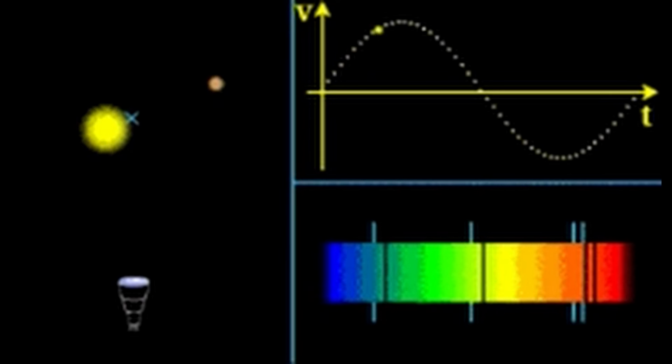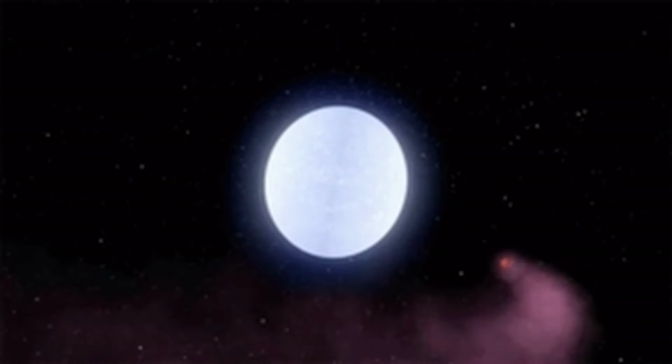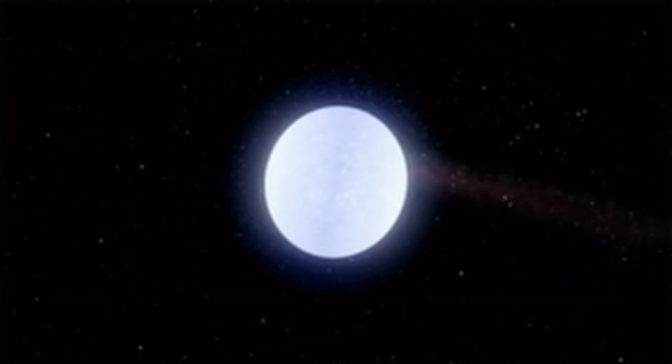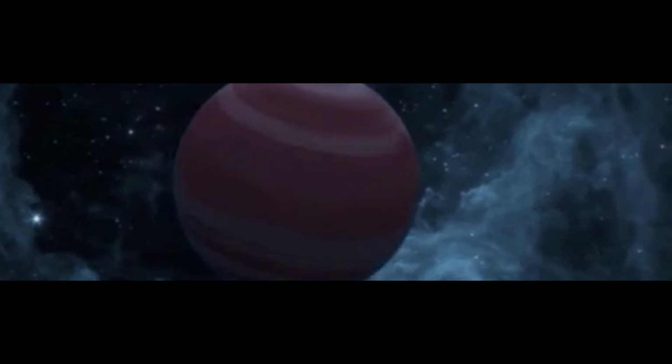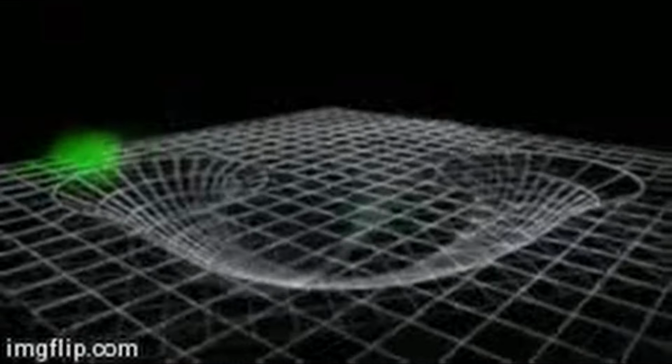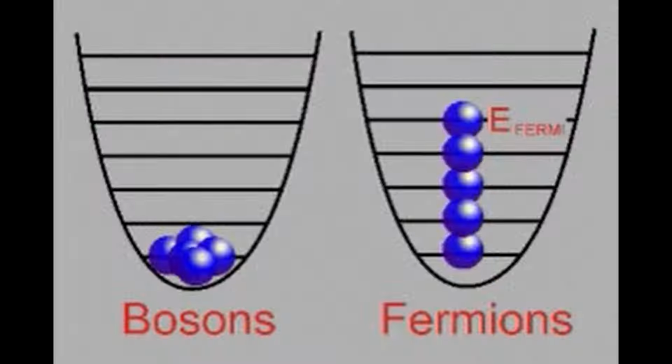5. Attenuation and absorption. In lossy materials, permittivity can be complex, with the imaginary part representing the material's ability to absorb electromagnetic energy. The complex permittivity, epsilon equals epsilon' minus j epsilon'', leads to attenuation of the wave as it propagates through the medium. The attenuation constant, alpha, is related to the imaginary part of the permittivity. Proportionality: higher epsilon'' means greater energy loss and stronger attenuation of the wave.